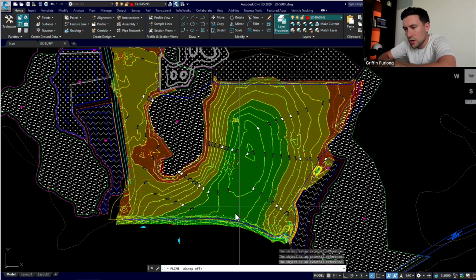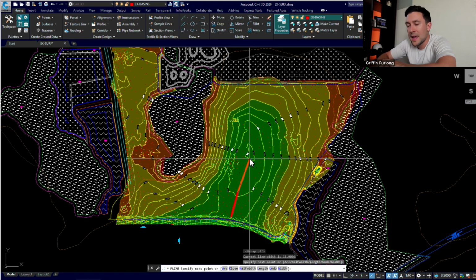So I kind of want to start our focus on this ridge. We've talked about this ridge numerous times here, and what I'm noticing is that there is a huge break line here where if water falls on any of these sides, it's going to either go west or east. So that's kind of where I just want to start this high level basin break. And again, I'm not really taking a rocket science approach here, guys. I'm kind of eyeballing it here, but I am going to follow perpendicular to these contour lines.